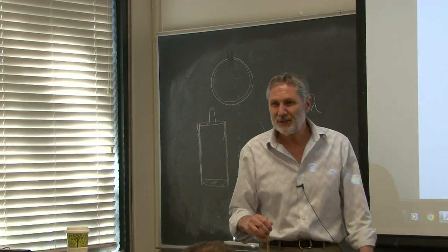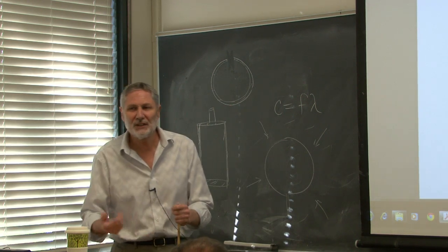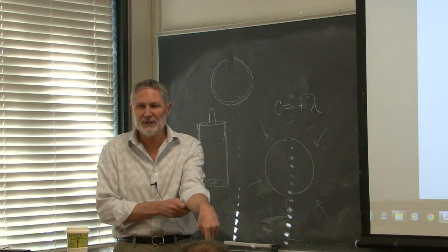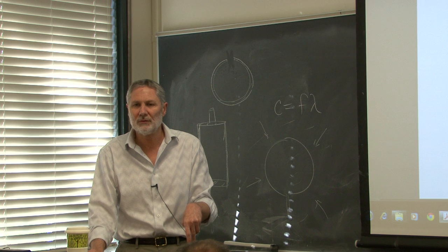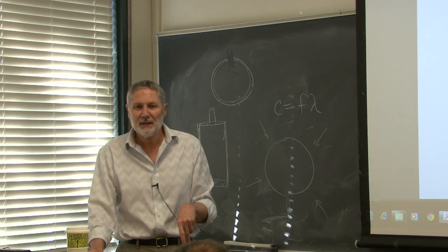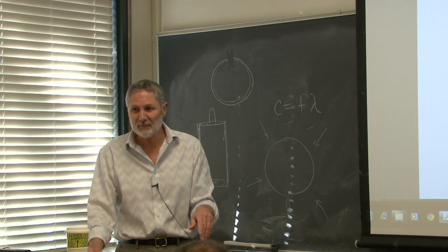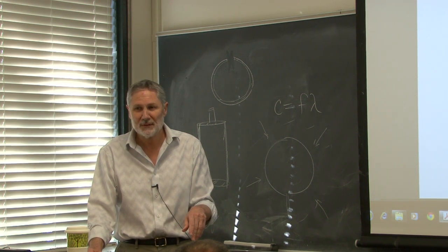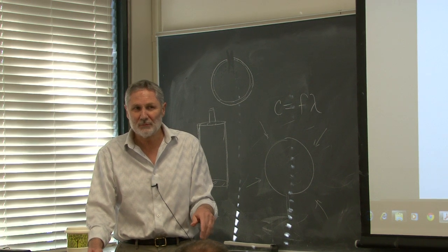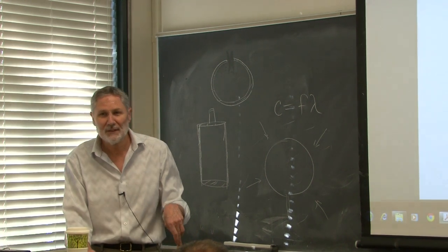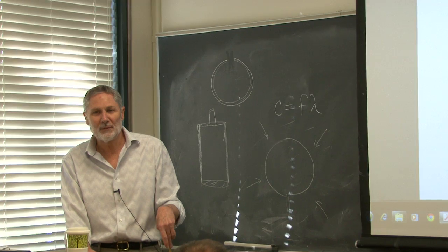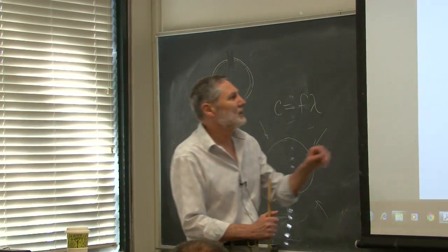But they took a highly linear LC circuit, modulated, I think in one case the inductance, in one case the capacitance, different ways. And they got parametrically excited oscillations, and they just kept growing. And before long, what happened? The circuit burnt out. The current was so great that the wire melted, okay?